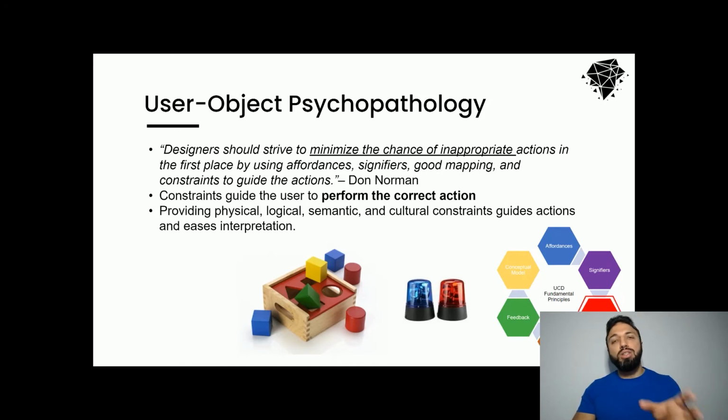This is actually good design, because if you think about it, you're going to get one kit, and if you have to think every single time which bolt to use, this is an additional effort I'm putting on you as a designer. Or if I'm going to do that, I'm going to make them completely different in size, i.e. I'm going to use M2 bolts in one location and M6 bolts in another location. So the difference is so big that it's super visible. You cannot mistake that bolt for that bolt.